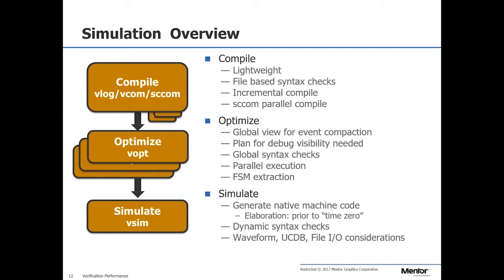If you have 15 processes that are all sensitive to the same clock and reset, it can merge all those into a single process and order the events correctly so that it simulates the same, but it's no longer needing to schedule 10, 15 processes, it's scheduling one process. And that can really add up to some massive gains.